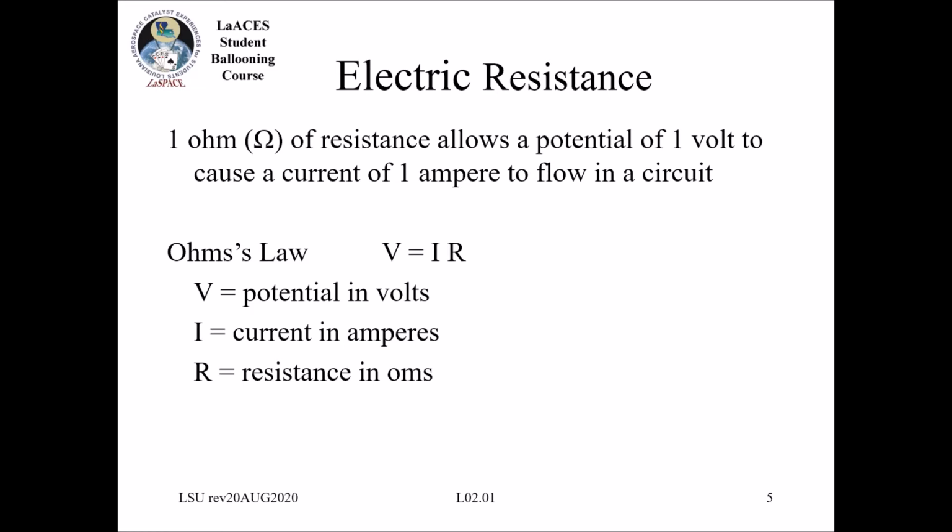So just taking a look at this, you can see that as the current or the resistance increases, the voltage is going to increase. But then you can also take the same equation and rearrange it, right? And so then you can get current equals voltage over resistance. In that instance, the current is going to increase as resistance decreases. So that's a really important relationship. Spend some time learning this. And then also our activity that we're going to be working with will also be dealing with this law.